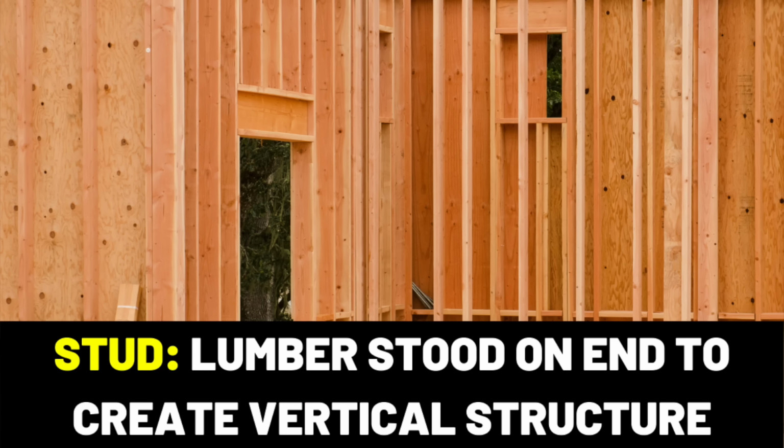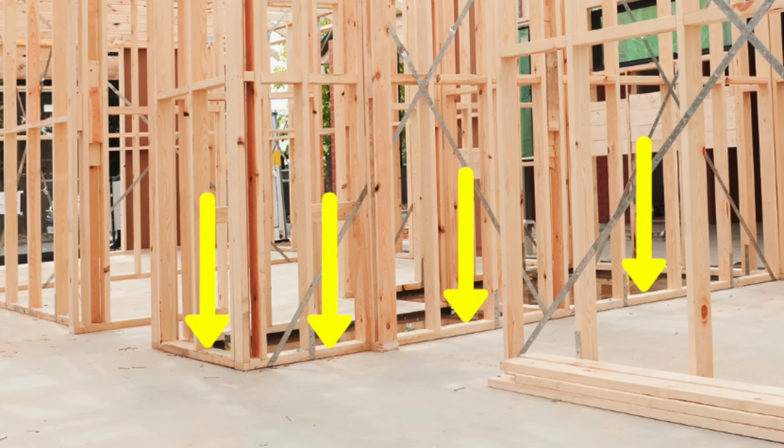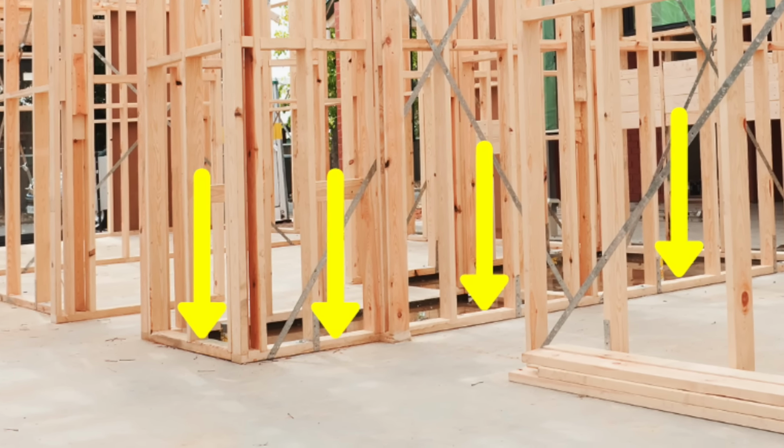But studs never actually touch the subfloor. Instead, they sit on another horizontal piece of wood known as a plate. A plate is basically just a stud laid down on its back. It's virtually identical to a mud sill, except that it's not treated because it's not in contact with wet masonry. This is just kiln-dried 2x4 or 2x6.